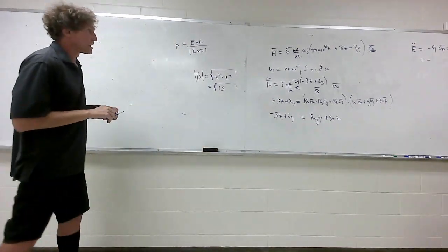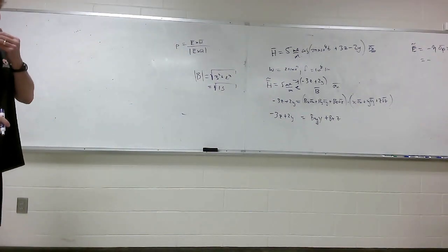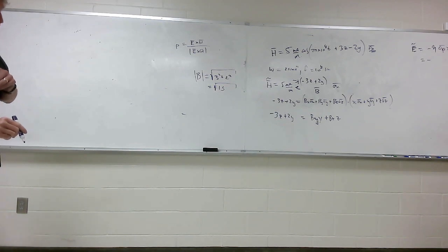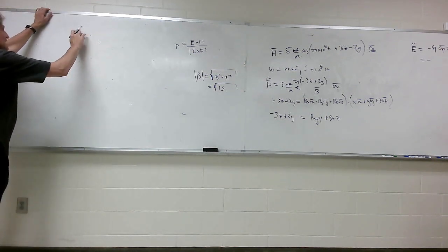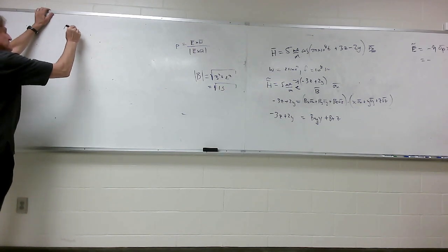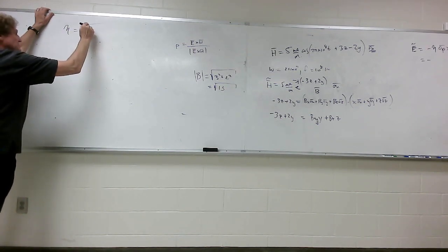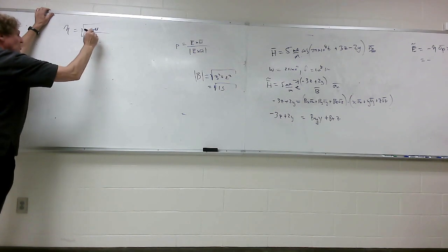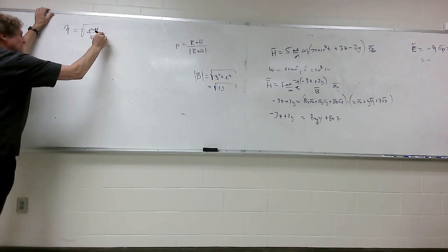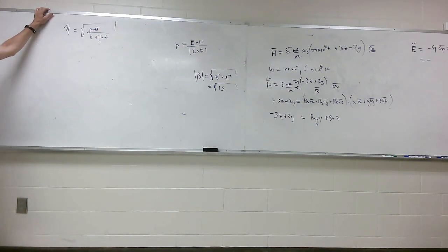So, got the H field, got the direction of propagation, got the phase velocity. Now, intrinsic impedance is equal to the square root of j omega mu over sigma plus j omega epsilon. That's the general form. Agreed, class? I said one thing, that it was lossless, right?